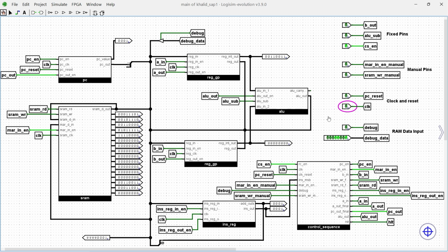We're gonna do this for our second instruction. Again 6 states, and then we're gonna see the address 14 value in register B. So 6 clock pulses again. 1, 2, 3, 4, 5, 6. As you can see, the address 14 value has been stored in register B, and the program counter has again incremented by 1. Then we have to do again 6 clock pulses for the third instruction to be executed. 1, 2, 3, 4, 5, 6.